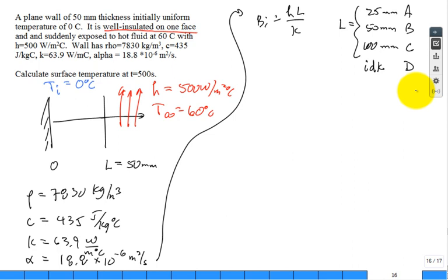Okay, now you calculate this Biot number. It comes in at 0.394. What should you do? Well, if you use the lumped capacitance, it'll get you in the ballpark. At this point, I recommend you use the lumped capacitance just to see roughly what we're talking about. But I would then come back and bulldoze through the math with the detailed solution and then know that they'll be comparable. Maybe not agreeing that well, but they'll be in the vicinity.